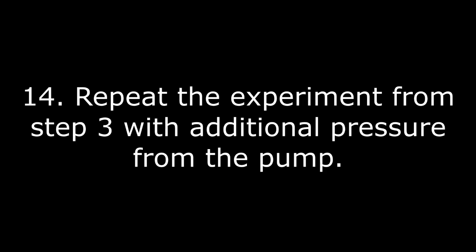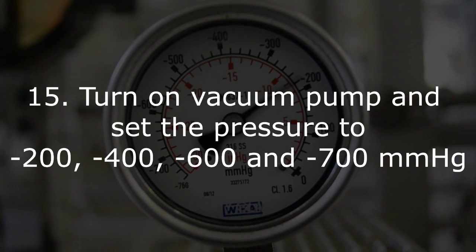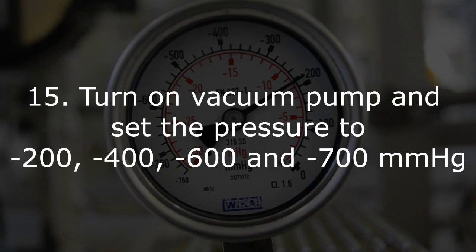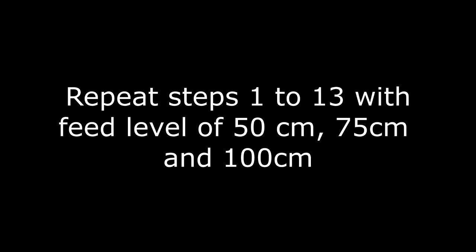Now, repeat from step 3 with additional pressure of pump. Turn on the vacuum pump and set at the negative pressure 200, negative 400, negative 600 and negative 700 mmHg. For part 2, repeat steps 1 to 13 with different feed levels of 50 cm, 75 cm and 100 cm.